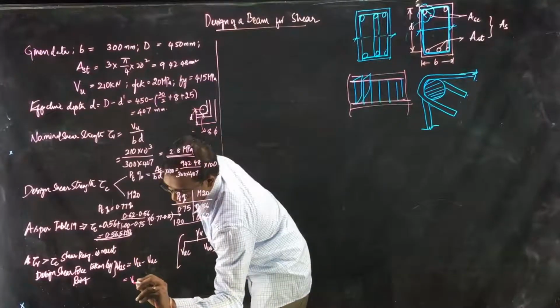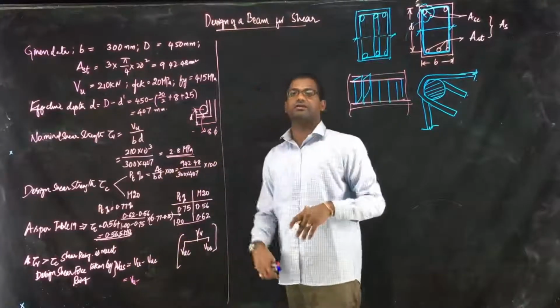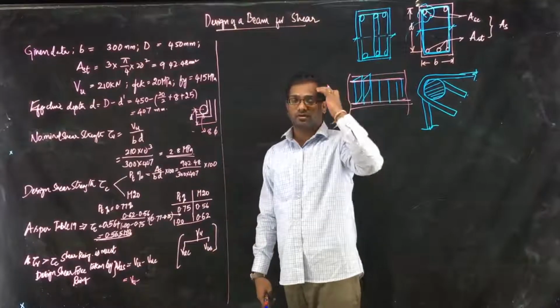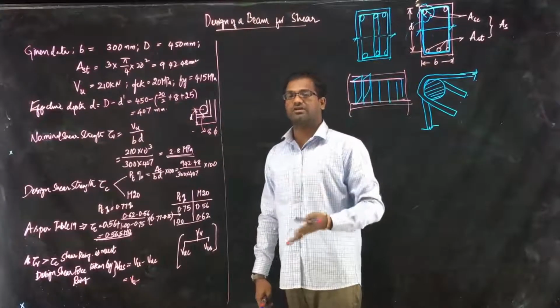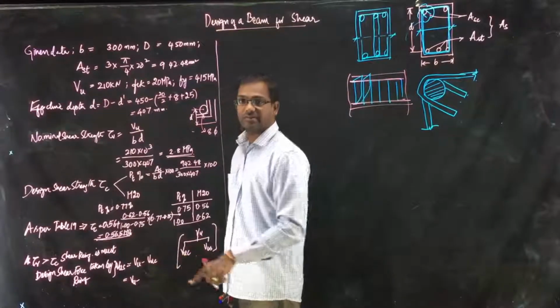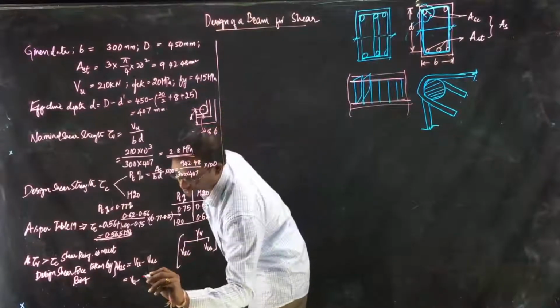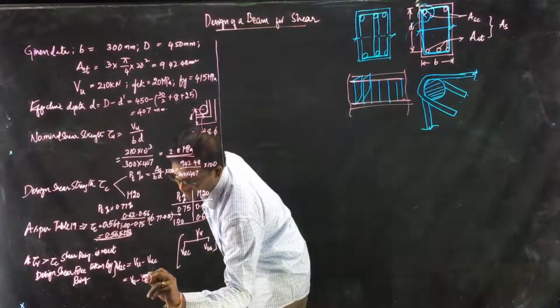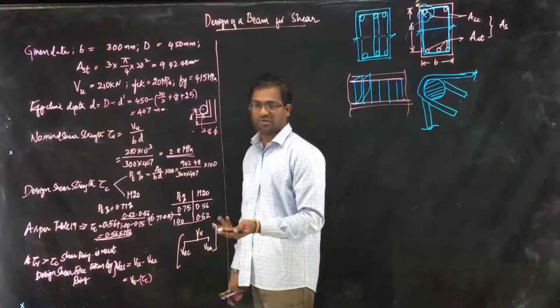Now how much shear force can concrete take? Force is given by stress into area. So you know the design shear strength of concrete multiplied by area.